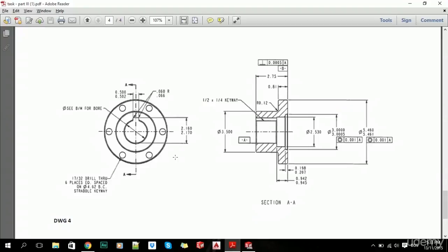There is. As you can see here, there is a fillet in here, but we don't have an annotation for it, so we'll just use our own, let's say 0.1. We have it here as well, and here as well, and I believe we have a chamfer here.